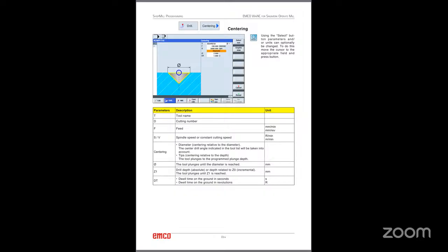And I have explained what retraction plane and safety distance are. The tool will be here and come to the retraction plane very fast, a very rapid movement. That's why it is red color. Red color means a very rapid movement, and it will reach the safe distance. Then from the safe distance, the tool will enter into the workpiece.